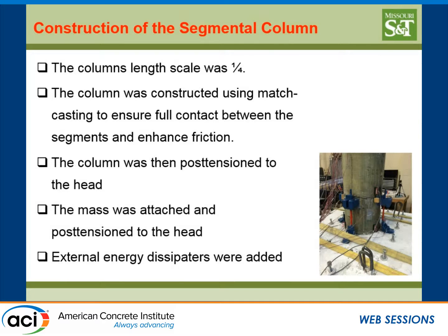So if this bar is in tension, it will expand and probably yield. And if it's in compression, it will just slide into the steel angle. And the steel angle itself is welded to the inner steel pipe. It looks ugly, but we're working on finding a solution for the shape of this. But again, the advantage is it's outside, so it's easy to replace. After an earthquake, if you have yielding and damage to the energy dissipators, you can replace them.